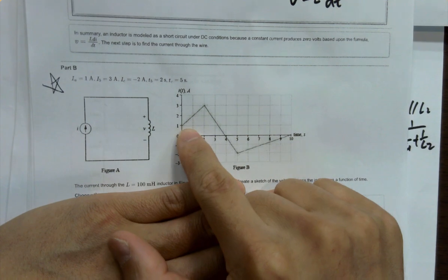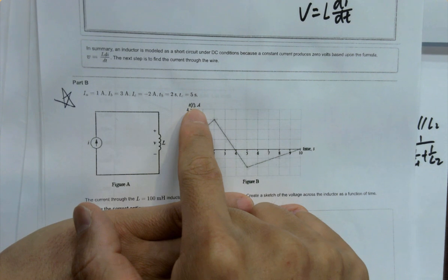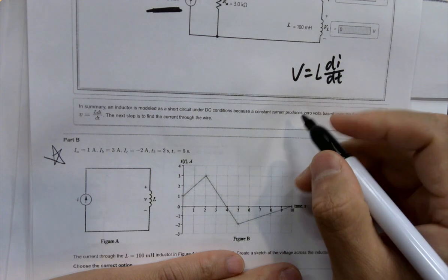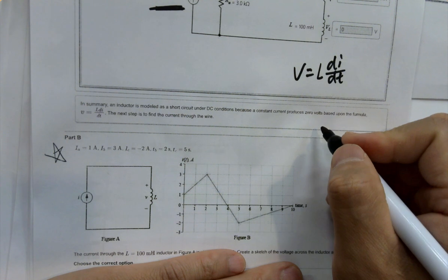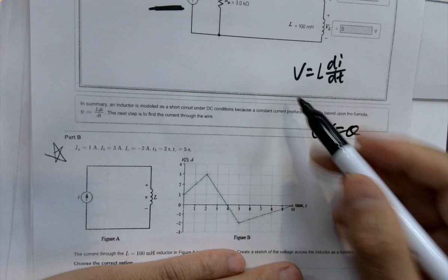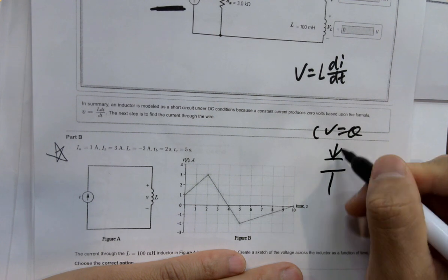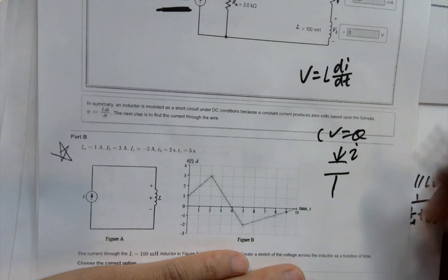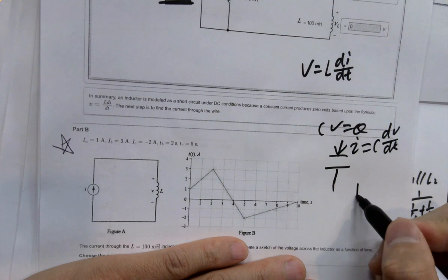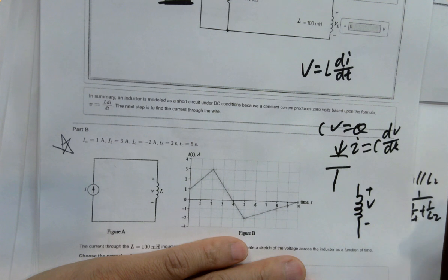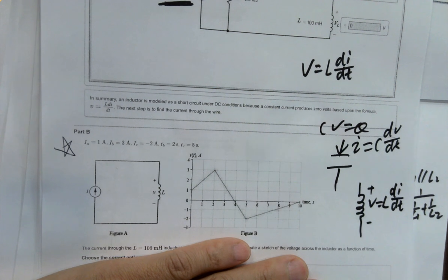It's asking if it's providing a ramp. So you can imagine it must be current, because of the dt. It's the alternating current this time. What's the equation to model a capacitor though? C equals Q over V, so CV equals Q, yes. It takes some time to remember all these models. We model the capacitor by the current I across it, so I equals C dV/dt. For the inductor, we model the V across it, and V equals L di/dt. I'll have to repeat it 100 times this semester so you can remember it.